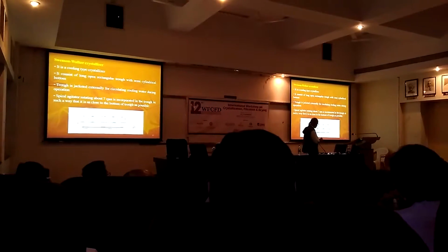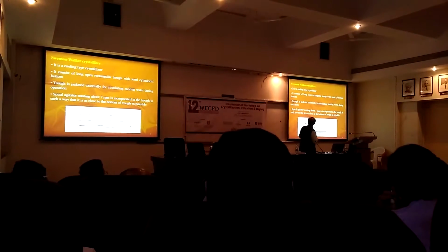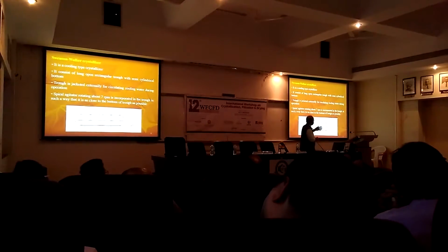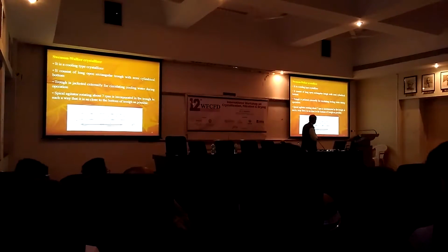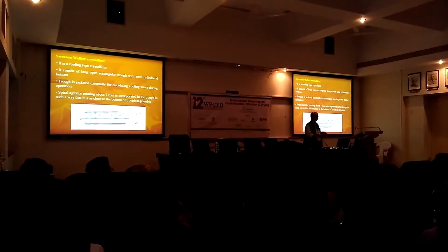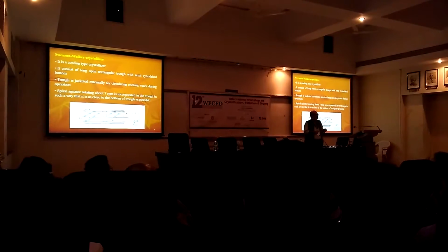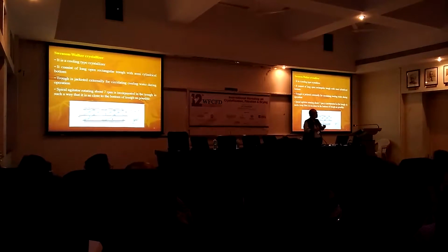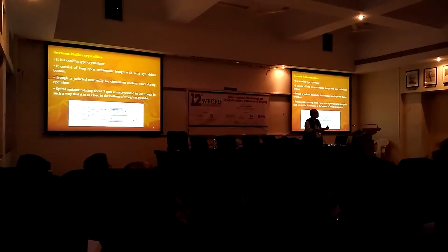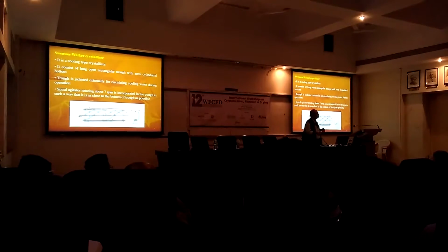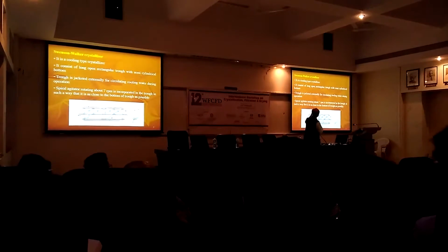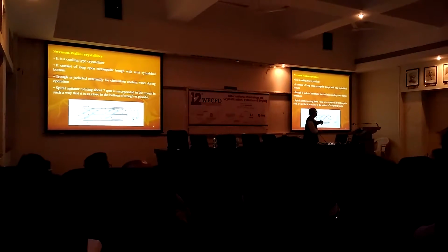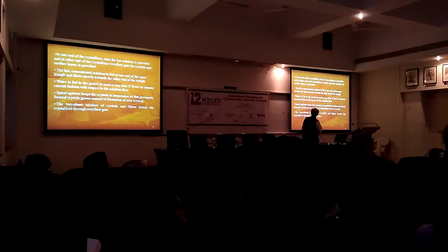Another design which is quite popularly used is the Swenson-Walker type of crystallizer. It's a horizontal trough where material enters from one end, and you can have broken jackets, and each jacket can be controlled to a different temperature level to get the rate of cooling which you require to achieve a specific size distribution for the solute which is crystallizing out. These are the typical numbers, and you can refer to this. These slides are available with you.